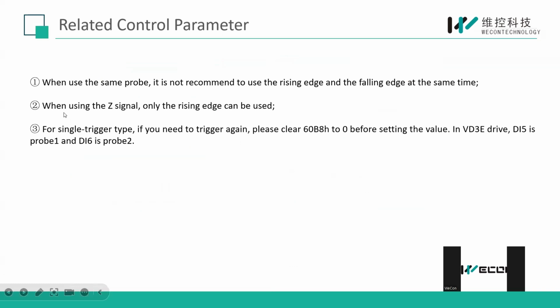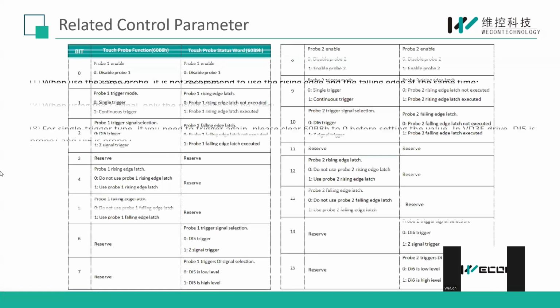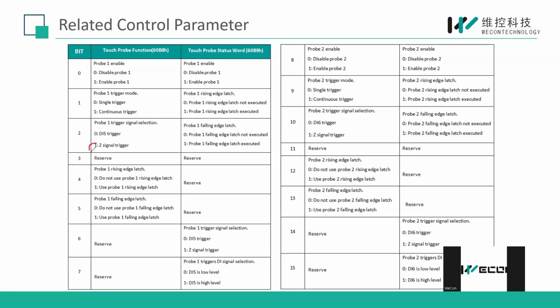And second, if you are using the Z signal, only the rising edge is supported. Here, if we use the Z signal to trigger, then we can only use the rising edge to keep the position.